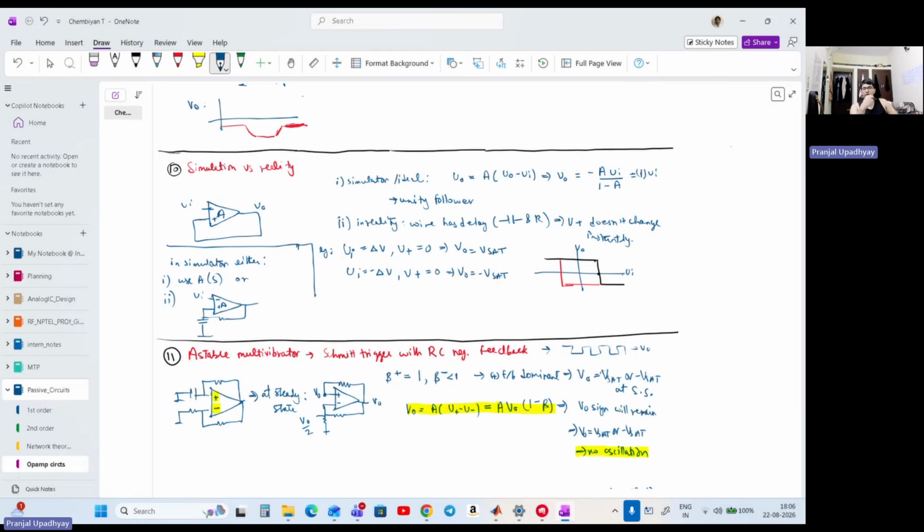It is something that we also do in our normal simulations, that we add some parasitic capacitance and resistance on our own, without first bringing the circuit to layout, so that in the schematic only we can estimate how much the wire parasitics will hurt us. So we intentionally put additional capacitances and resistances in the circuit so that we could plan the design in a more optimized way. And then when the circuit actually goes into layout, we try to pre-estimate how the parasitics will increase.